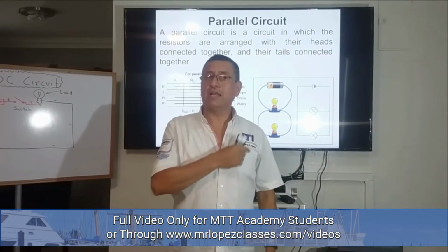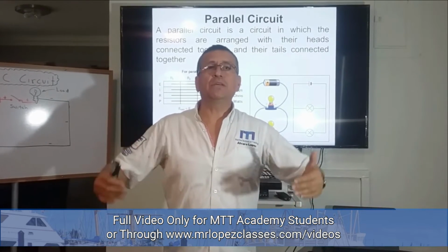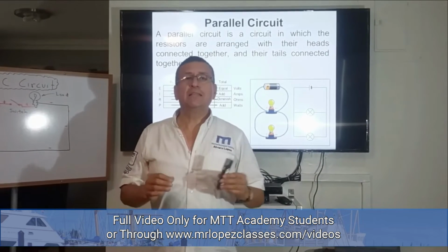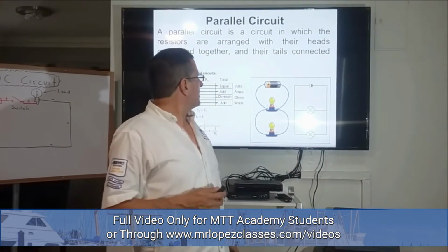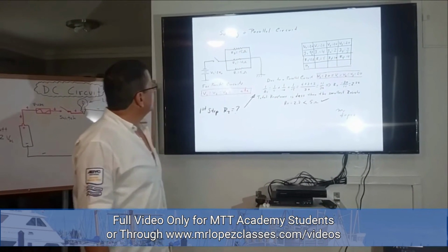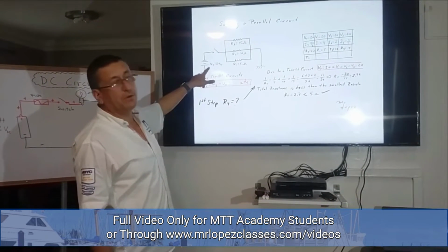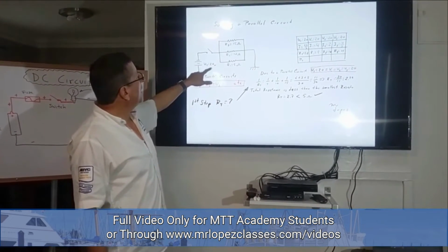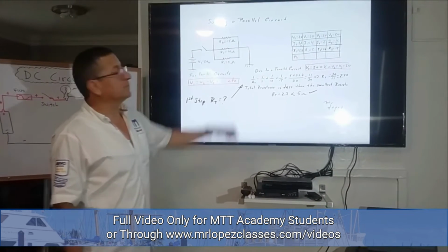And you remember when you connect batteries in parallel, what element increases? The intensity, the amps increase in parallel. And what is constant? The voltage is constant. It's exactly the same right now in the circuits. I have a circuit in parallel. I created that circuit for you, exactly the same. The input information is exactly the same as the previous one, 20 volts on the battery, and I have three resistors, 5 ohms, 10 ohms, and 15 ohms.